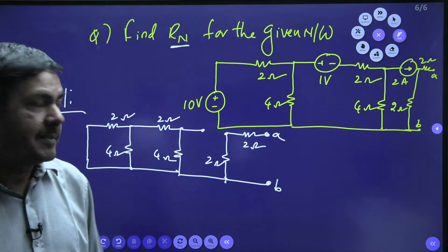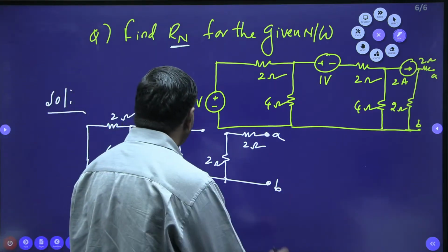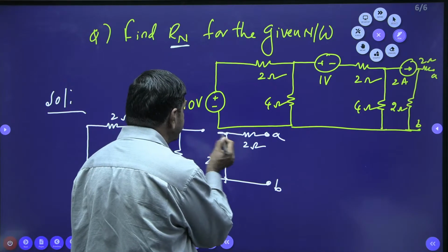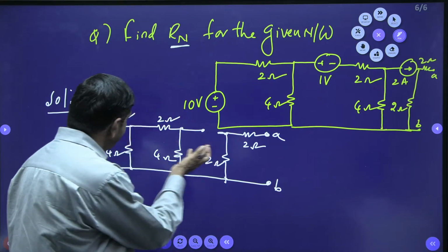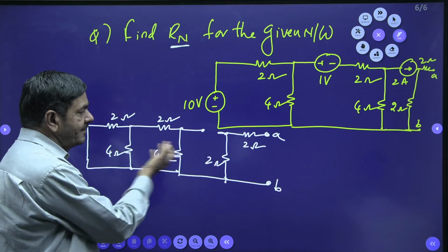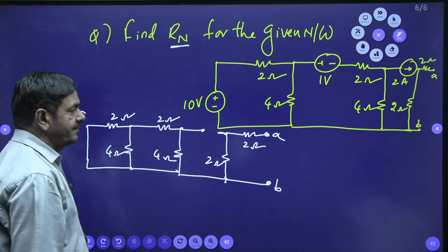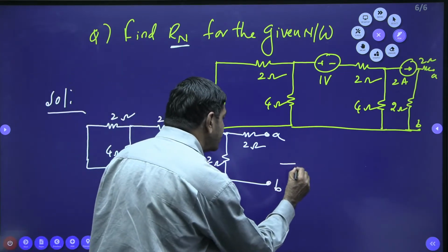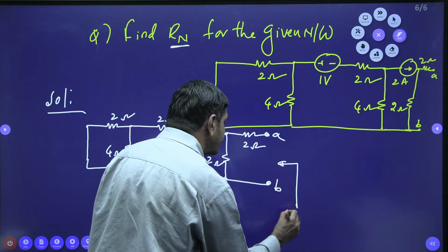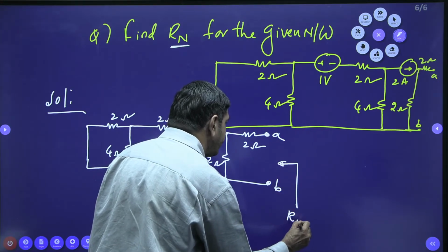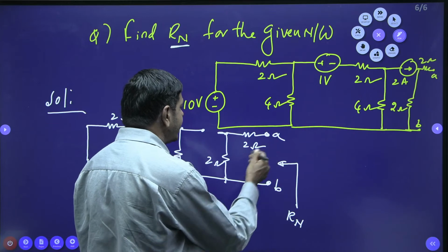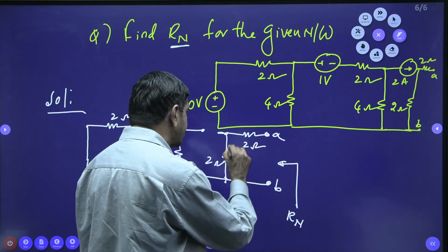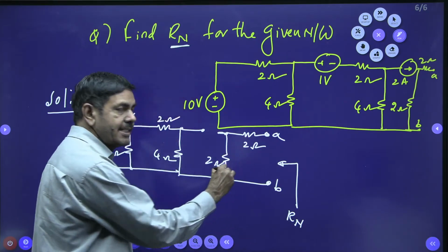But yes, you are saying, Manoj. Please watch. Whenever this current source is open circuited, this will be useless. But I want the resistance across this AB. That is Rn. Resistance across AB is required. Resistance across AB means these two are in series.